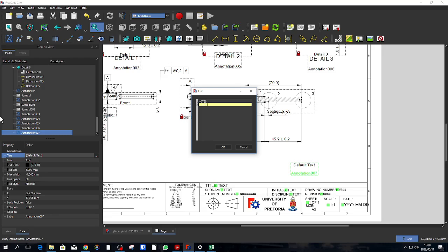Surface roughness to be RA 3,2 unless otherwise specified. 2. To break all sharp edges to 0,3 max.